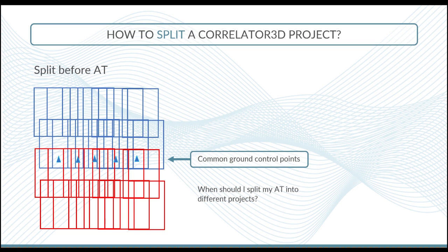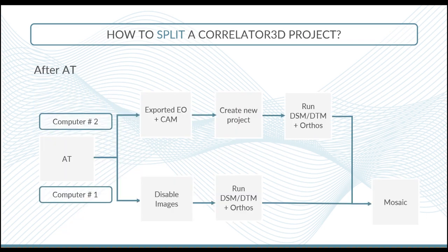So most of the time, I think that you should try to run the aerial triangulation in one single block in Correlator3D. Now, what would be maybe more common is to split the Correlator3D project after the aerial triangulation.